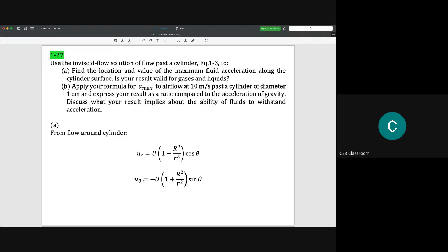So this idea actually comes from when we studied the ideal flow. We have linear source, sink, and vortex, and then we merge the sink and the source, we get the doublet, and then we combine a doublet with linear, then we get the flow around a cylinder. And if we add a vortex inside the stream function, meaning we have doublet plus linear plus vortex, it will show the flow around a rotating cylinder. So I hope you still remember that.